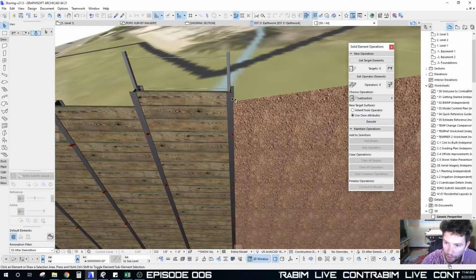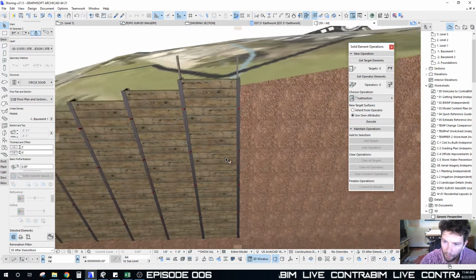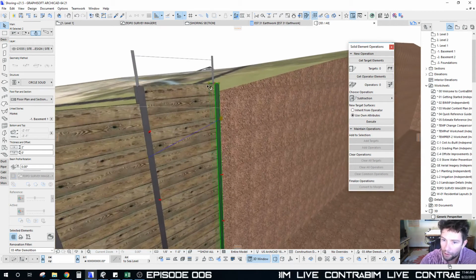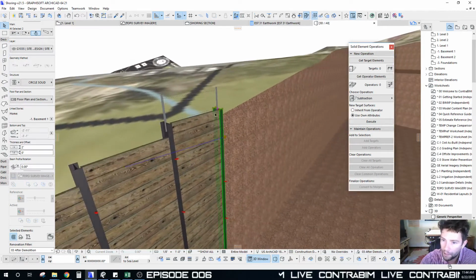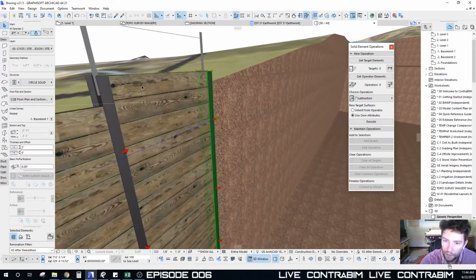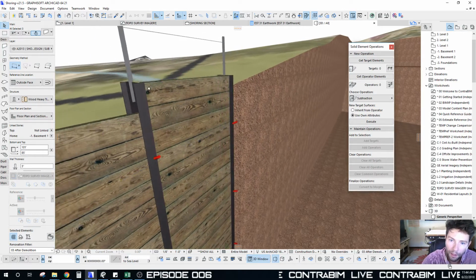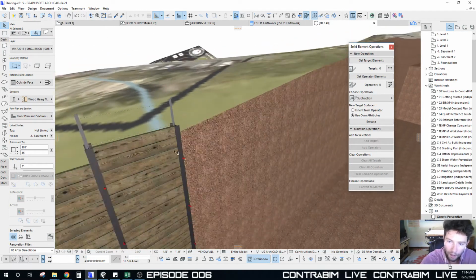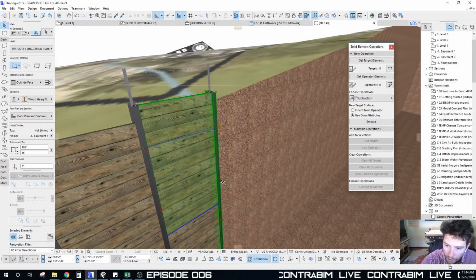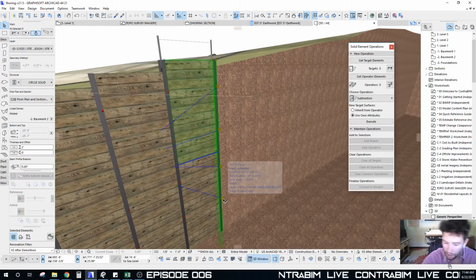And okay, so actually one thing I'm thinking about right now: if I'm taking this shoring and pulling it up this slope, if I did it from this side and copied this, then on the next one up we're actually going to have this legging overhanging on this side. So I found that it's a little quicker in this case to multiply it in the other direction.